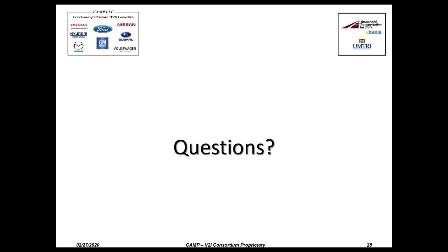One nice thing that the emissions model DLL was able to do for us is send emissions data back into Vissim. We were able to read it directly within Vissim. Now, it doesn't send it back into all locations, and I actually don't remember which exact locations it sends to, but it's all in the manual. So the emissions model DLL allowed us to use our own code to represent the MOVES algorithm. And so you could use something other than MOVES with the emissions DLL if that's an important part of your project.